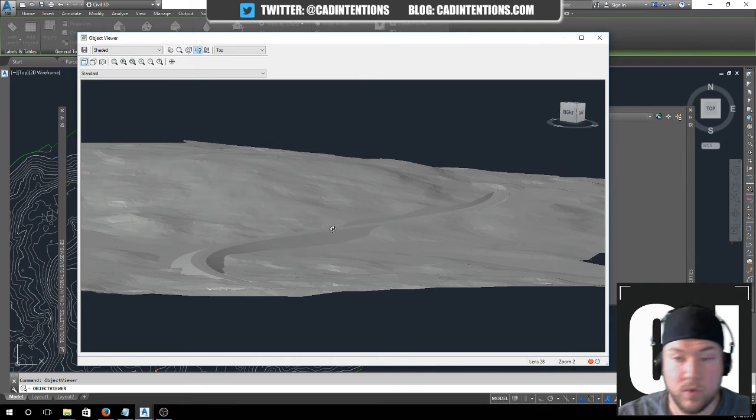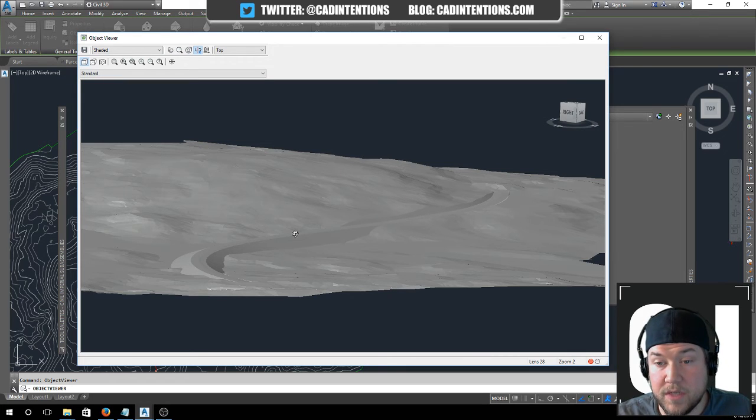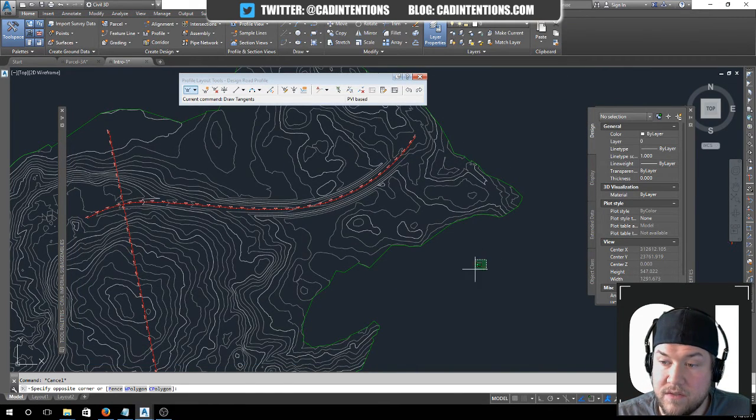So depending on what you had for material, you might want more cut, or what's more likely is you want to balance the amount of cut with the amount of fill that you're going to need as much as possible. But sometimes the material you're cutting is unusable, so that doesn't really matter. Sometimes the site has a ton of excess, a surplus of material, and you can use it as fill. Sometimes there are other reasons, but you kind of get the gist of it. You can switch things around.